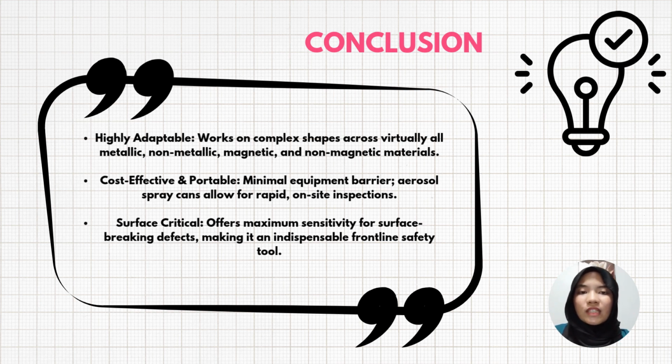Another important advantage is its high sensitivity for detecting surface defects. Even very small cracks, pinholes, and other surface discontinuities can be detected effectively, helping to prevent failures and improve product reliability. However, this method is limited to defects that are open to the surface and cannot detect internal flaws hidden beneath the material.